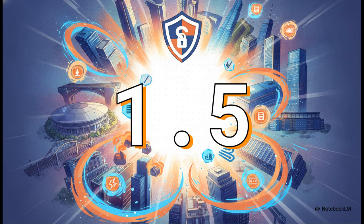Now check out that massive 1.5 right there. When we're designing for the ultimate limit state, we don't just use the expected everyday weight of the building. No way. We magnify our characteristic dead and live loads by a factor of 1.5. This guarantees a massive safety buffer for those extreme, totally unpredictable events. We are mathematically preparing for the absolute worst-case scenario.